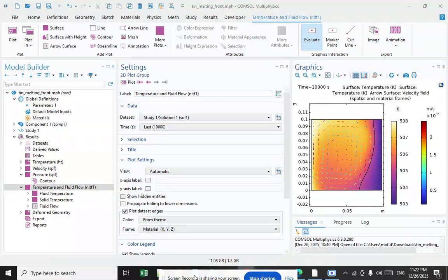A peritectic transformation, in which a two-component single-phase solid is heated and transforms into a solid phase and a liquid phase. A peritectoid reaction is a peritectic reaction except involving only solid phases.